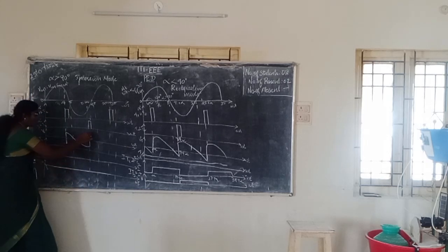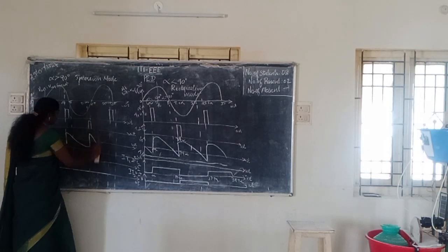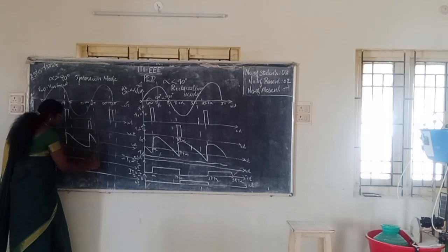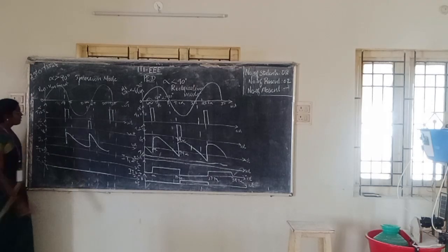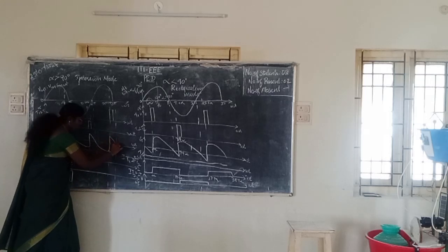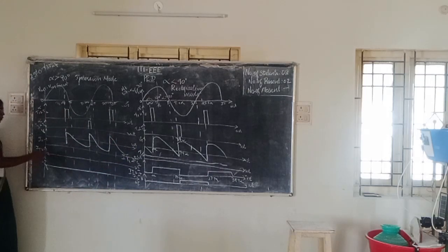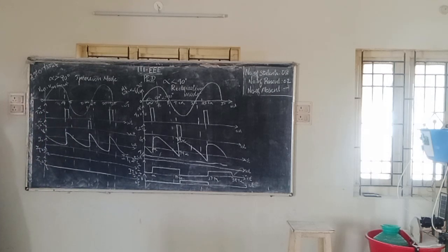So the voltage will rise again, and again it will reach zero at pi over here. It will reach until negative at 2 pi plus alpha is given now. Can you follow me? Likewise, again it is zero and it will follow. This will continue. This is how the output voltage waveform looks when alpha is greater than 90 degrees, that is, during inversion. Next is the current through T1 and T2.